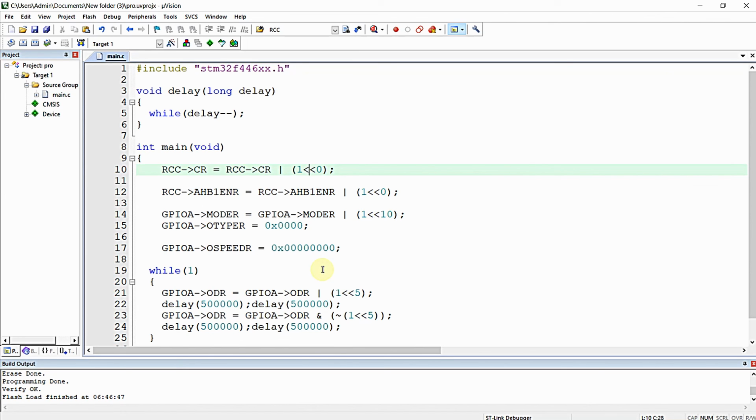So we successfully wrote the program for blinking the LED using the CMSIS file from the silicon vendor, and from here on we will be utilizing this CMSIS file provided by the silicon vendor, because this is very important. You must learn how to utilize the CMSIS file provided by the silicon vendor, so that you will be able to program any microcontroller using it, rather than creating your own CMSIS file, because that consumes a lot of time.